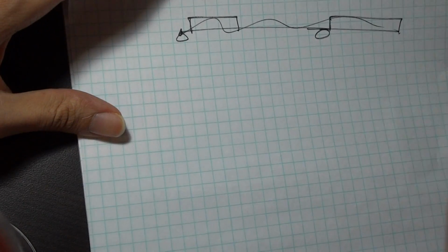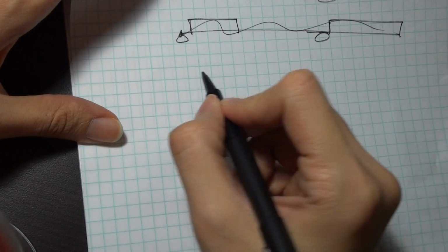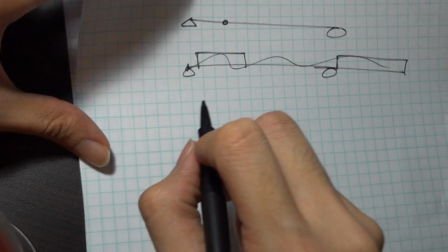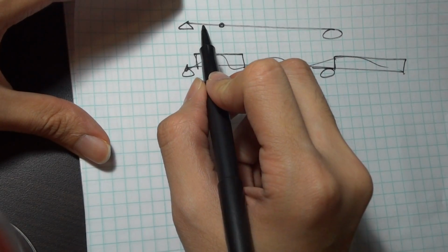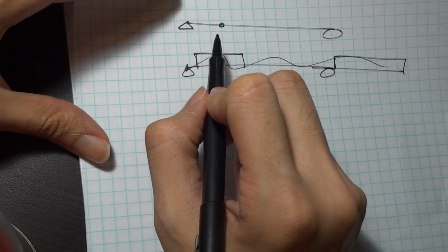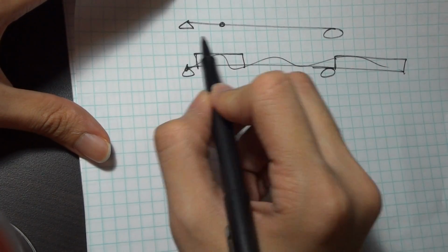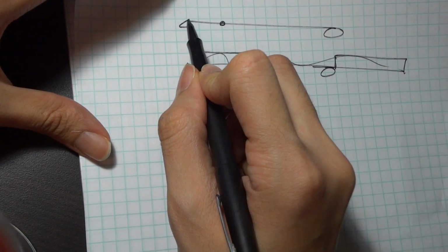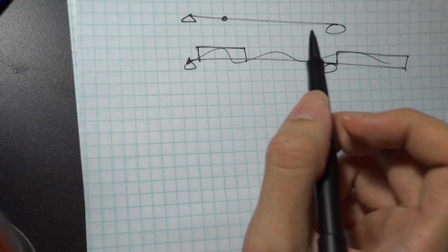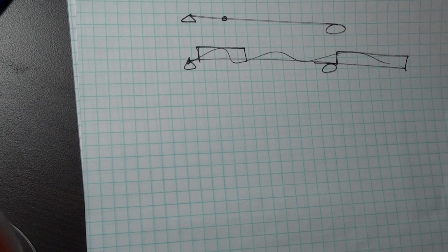To actually solve for influence lines, I'm going to be using the Müller-Breslau approach here. Müller-Breslau just says that if we treat our beam physically, if we force it to obey the initial boundary conditions and force the individual elements to remain rigid, we can get the shape of our influence line diagram by just applying unit rotations and unit deflections. So what do I mean by that?